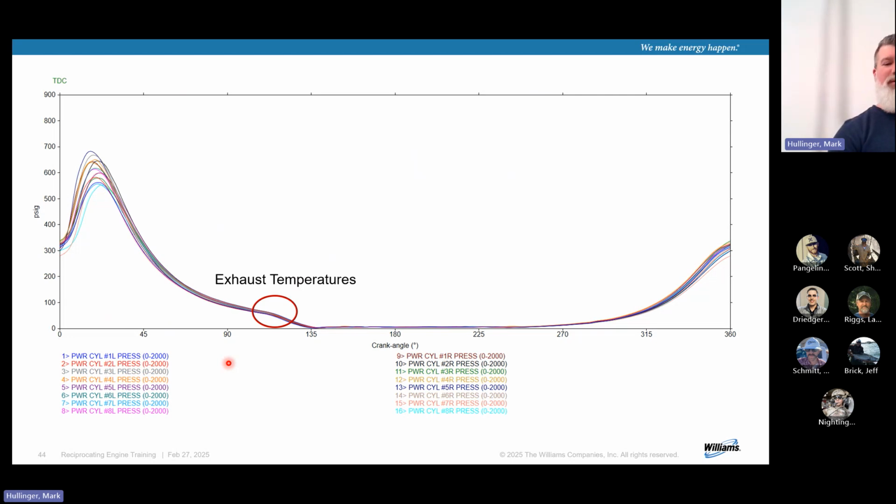They're going to be close. They're not exactly the same, right? But where we put our temperature probe is right here, not right here. So can you balance off exhaust temperatures? You can try, and boy, do we try, right? Balance and then adjust for your exhaust temperature. Yeah, you can do that.